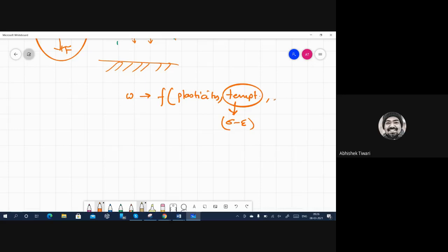Apart from that, we usually do the test at a certain strain rate. Even then, as we did in our lab, you put the tensile specimen in the machine and define a loading rate, let's say 0.5 millimeter per minute.